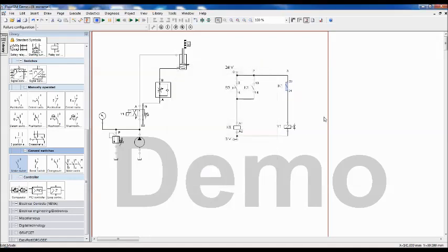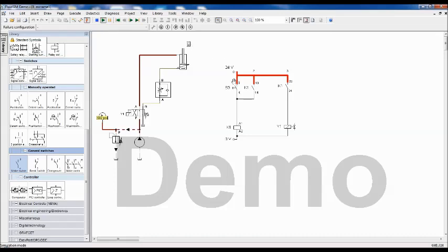So I'll just simulate this part. Let us see what is the significance of the proximity sensor. Go to simulation. If you press switch S5 once, that is enough. The cylinder is continuously moving upward and completing the full stroke. But our requirement is not the full stroke, only half of the stroke. So we have placed the B1 sensor exactly at 100 mm displacement, right?